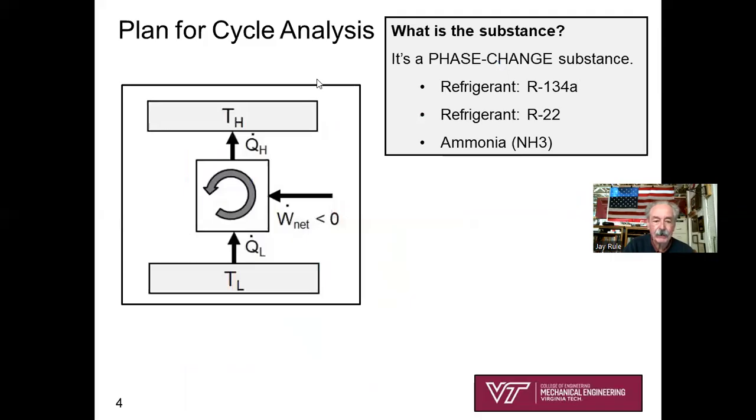Now let's see, all of these things. Let's plan for what we're going to analyze before we get into the nitty-gritty details. Always, always, when you have an engineering problem associated with a heat pump or refrigerator, draw this schematic sketch. It helps remind you that you're transferring heat from a low temperature to a high temperature, which seems kind of strange, at the expense of needing power to drive it. So that's a key. Start with a sketch.